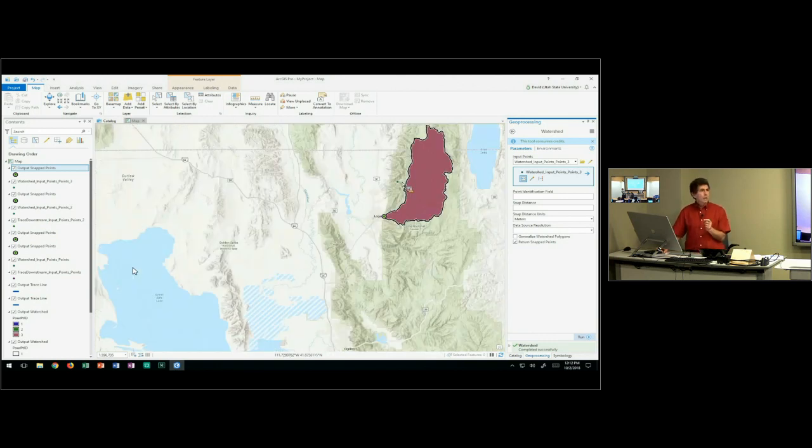What we'll do for the exercise is basically delineate that so that you know where you're working. This gives you a quick and dirty boundary. We'll put a buffer on that, and then we'll extract the DEM and do a more careful analysis based on that. So that's a bit of a preview for the exercise.